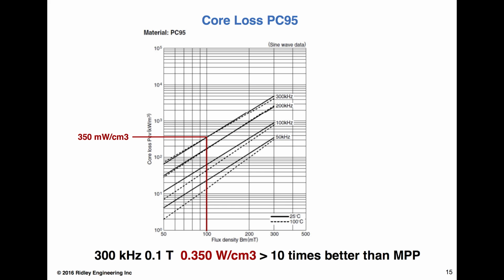Well, there's two things going on here. When you're running at a B max of 0.3 Tesla, you're probably not going plus minus 0.3 Tesla unless it's for something like an LLC inductor. So you tend to have a DC saturation, but your AC ripple is not going to be that full amount. And then one of the standards that's in the industry is when we look at the excitation level of 100 millitesla, this is actually a plus minus 100 millitesla.